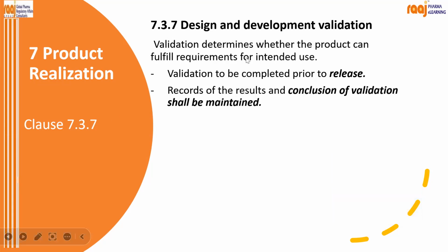Then validation determines whether the product can fulfill the requirements. Validation has to be completed prior to release. So you have to show that it is giving consistent results, like three validation batches, three consecutive batches we have to do for this validation.